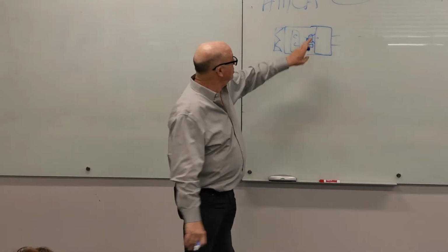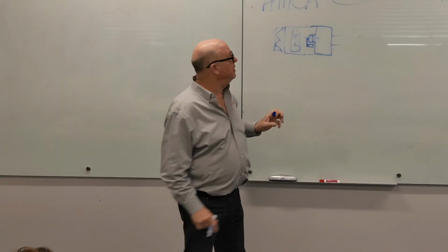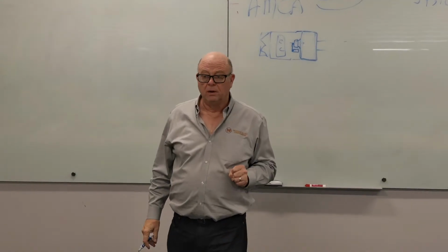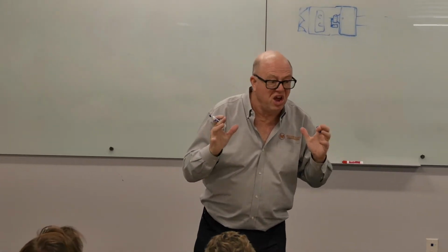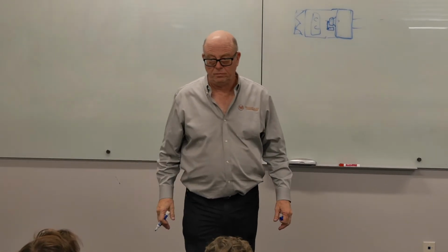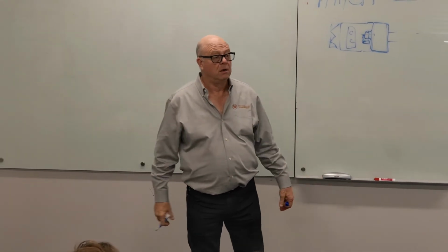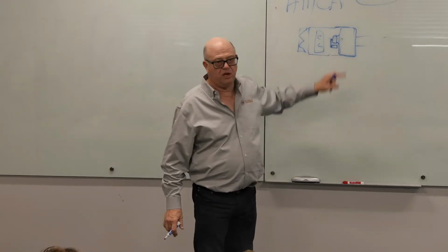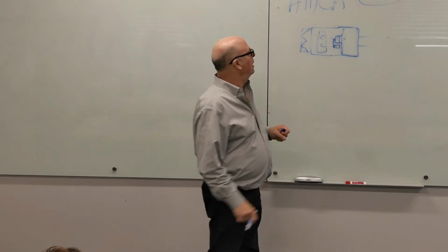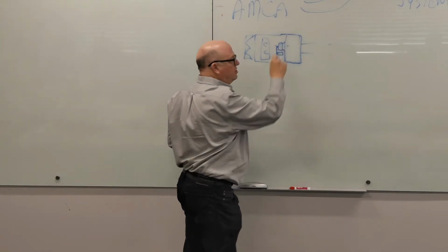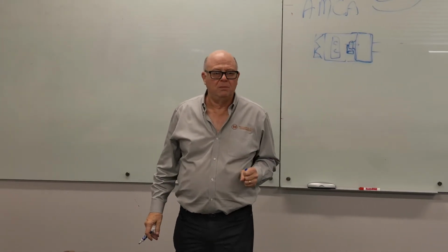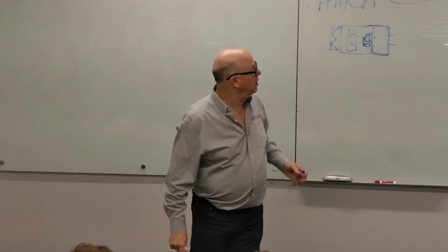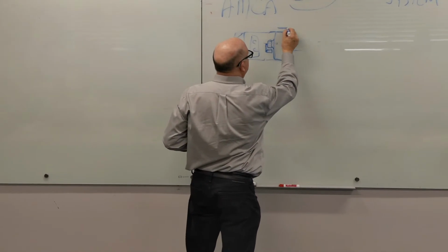One of the reasons that one of these is more expensive is because this piece has to be built hell for stout. You are pressurizing the heck out of that plenum. And that's part of the air handler, so it's got to be built really strong, okay? And so that's one of the reasons why this design is always more expensive. But it also takes more power. I mean, the waste inherent in doing this is significant. But you get two huge advantages.